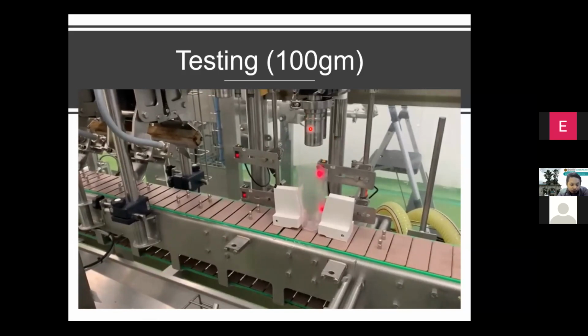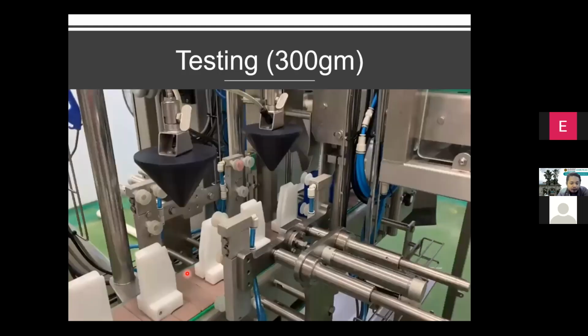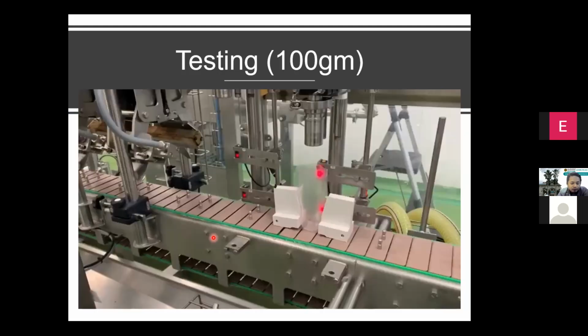So at the nozzle, the first step is blowing. The blowing is to make sure that the pouch opens and the food holder will hold the pouch open. This is actually very important for the next step, which is the filling. And sorry, this one is for 300 gram.